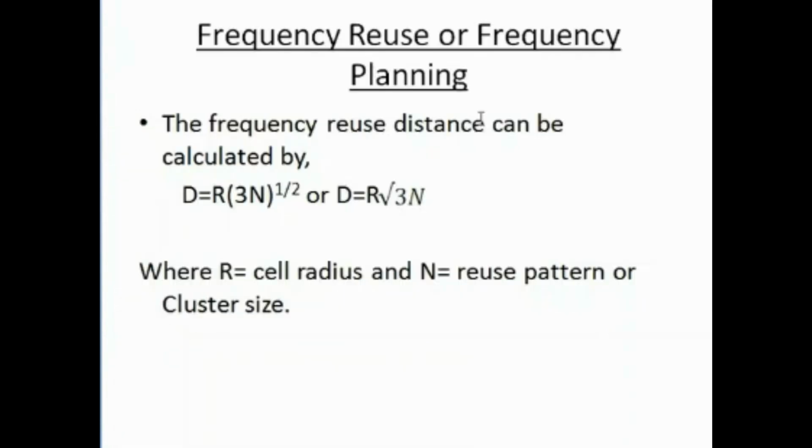In an attempt to gain the maximum reuse of frequencies for a cellular system, cells are arranged in a cluster. To determine the minimum size cluster that can be used, it is necessary to calculate the interference level generated by co-channel cells. Since there are several options for the size of a cellular cluster, a relationship can be determined that relates cluster size, cell radius, and reuse distance.